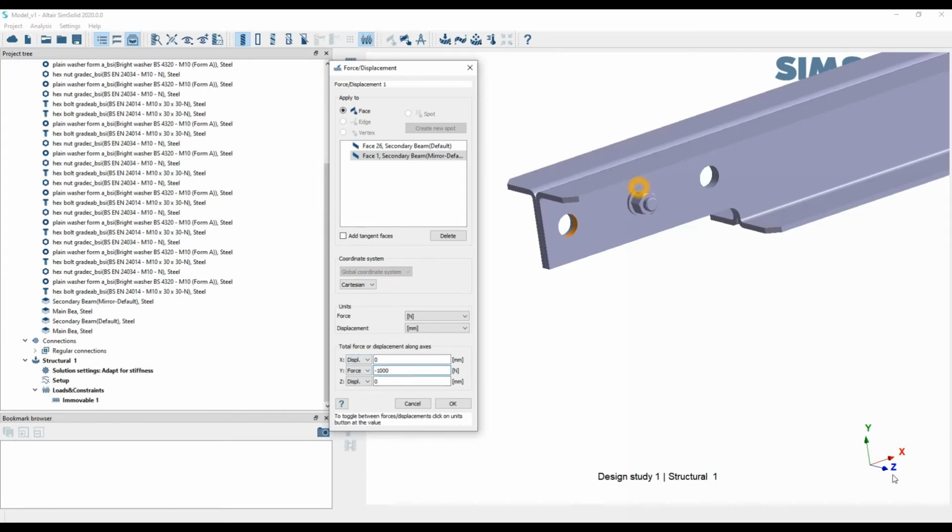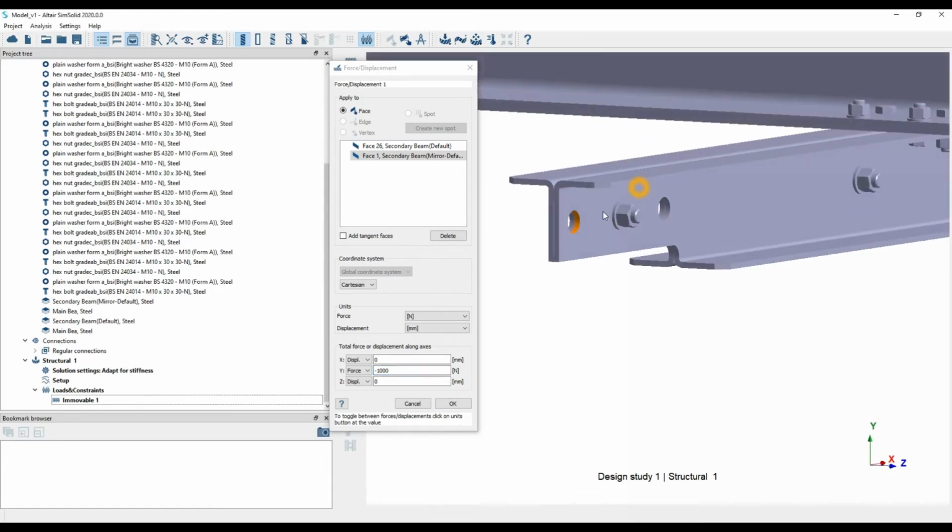Obviously minus because we can see the global axis, it's positive upwards, and we want it to be acting downwards. So we can see positive Y goes upwards, just like that global axis here does. And obviously if we want our forces to be acting downwards on it, then we need to specify it as a negative value. So that's why we put negative 1000 newtons, and if we put displacement of X and Z in 0, that means it will only ever displace downwards in Y.